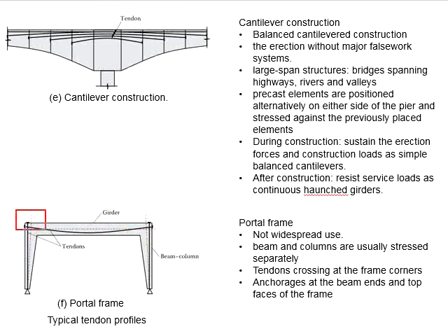This will behave as the condition of an intermediate support, which normally you will require the negative eccentricity. You will require the positive eccentricity at the midspan and negative eccentricity at the end span. Therefore, normally the tendon here is provided with negative eccentricity at the end span and positive eccentricity at the midspan.